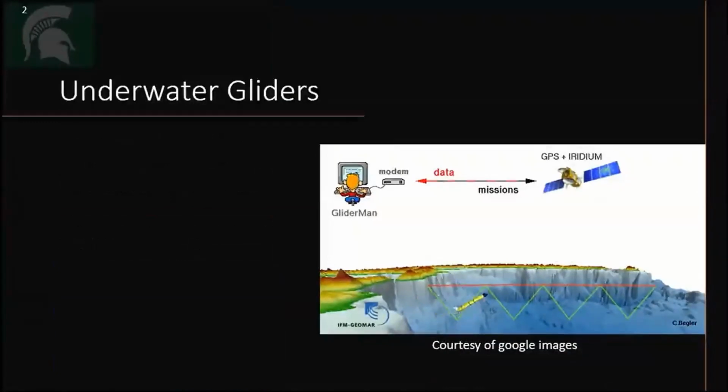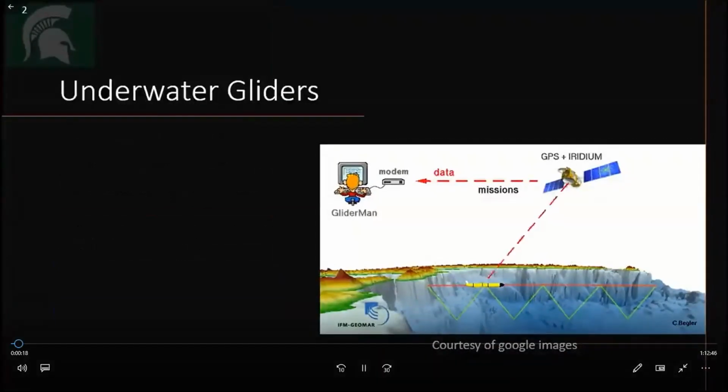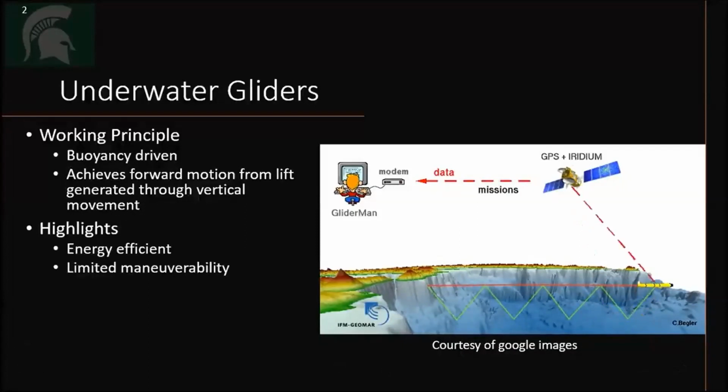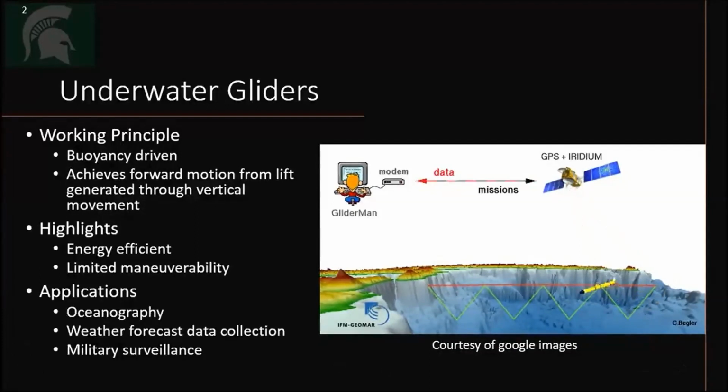Gliding robotic fish belong to a class of underwater vehicles called underwater gliders. These are autonomous, buoyancy-propelled vehicles that achieve forward motion through a combination of modulating pitch and changing the depth. They can be steered through control surfaces, such as a rudder, or by shifting weight internally to induce a roll angle. Gliders are known for their energy-efficient gliding and spiraling motions, allowing them to operate for weeks at a time. And over the past few decades, they've become valuable tools in a variety of applications, as seen here on screen.